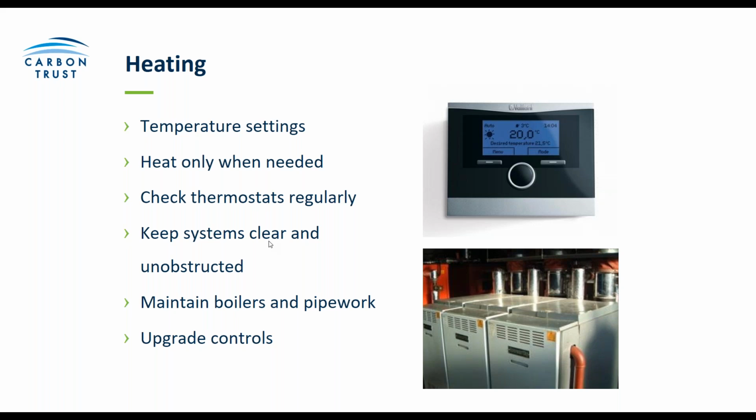And also make sure that boilers and pipework are well maintained. As a minimum legal requirement, gas-fired boilers need to be serviced once a year. Oil boilers would be twice a year. And a regularly serviced boiler can be around about 10% cheaper to run than one that's not being maintained.